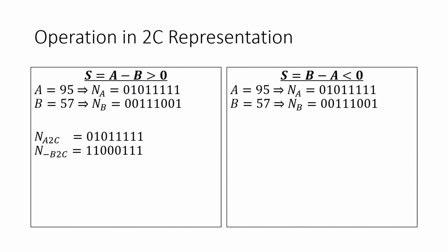Here we are showing you a minus b because that will reveal two things. One is the twos complement representation of a positive number. Second is the twos complement representation of a negative number. Then we will perform the simple addition algorithm on the twos complement representations, and we will learn to interpret the result.